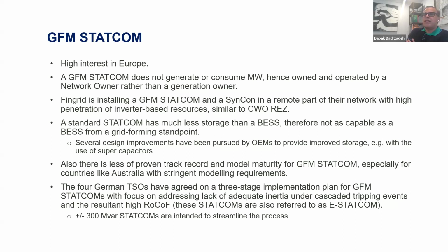Now, the second point is important because we have exactly the same thing with the STATCOM. So again, it's not a huge energy storage, not anywhere comparable to a battery, but it's similar to what you have with an HVDC link. So therefore, it might be argued that, okay, if this doesn't have as much storage, then probably it's not going to be as good a grid forming technology. And that may or may not be the case, basically.